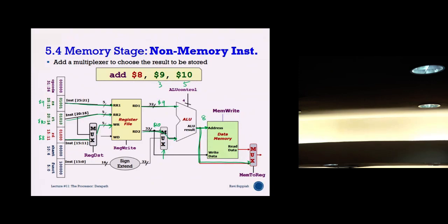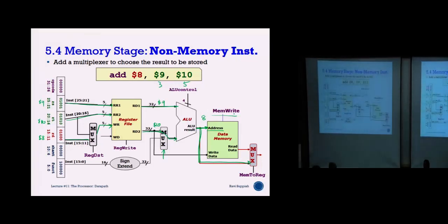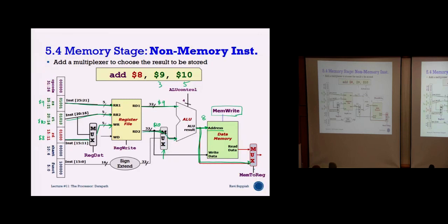Okay, so this value 8 will come to this memory and trigger the address bus, correct? Okay, so what will happen? Okay, that means the data in memory 8 is activated. Okay, but since I do not do any memory write or memory read selection, the data is not going to come out. So even though I present this value to my data memory, I still do not need to worry about it because I did not trigger the memory write or memory read,